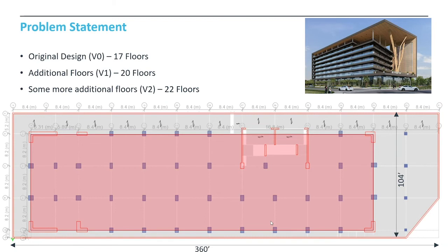Ashish, I have a question. This is Mazi from Canada. My first question is about the tolerances of the existing structure where you were reinforcing. How did you model that in your ETABS model? The other question is, when you were reinforcing, changing the profile of the existing structures or adding sections to them, how did you establish the quality and performance of the existing materials used on site?